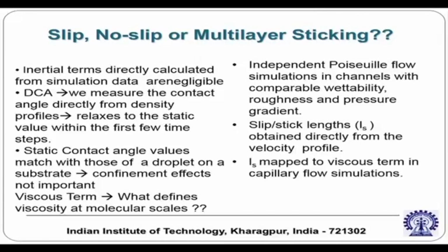To get the slip, it is very difficult to directly get the slip length from the capillary filling problem. So we try to apply an equivalent driving force and predict the slip length from the corresponding pressure driven flow simulation. How do you predict slip length from a pressure driven flow simulation? You have a pressure driven flow, you extrapolate the velocity profile and see where it matches the zero condition; from the wall to that length is physically the slip length.